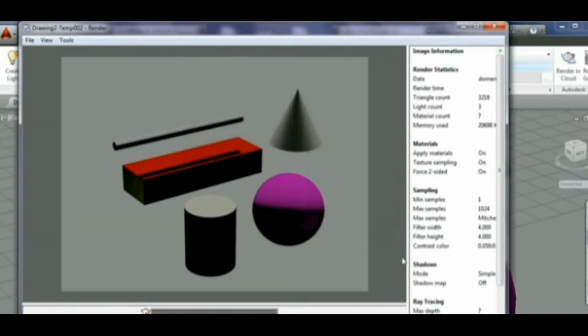On the Render window, the white squares you see are the parts of your project that are being rendered by your processor. And you can check the render status through the bar right at the bottom. Remember that only the portion of your project that you see in your workspace is rendered when you press the render button. The render will report all illumination and filling settings. What is not reported is the horizon, which is made through a color change in the sky, if enabled.